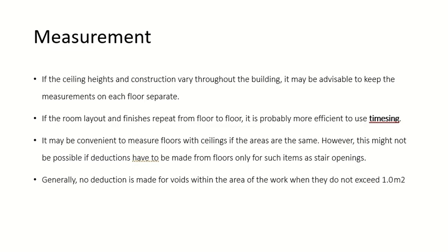So your floor may have an opening. You can do the deductions later on. But deductions are only done if the opening exceeds 1 square meter. If the opening does not exceed 1 square meter, then we just ignore it. It is just part of the wastage which you have to consider in your project.